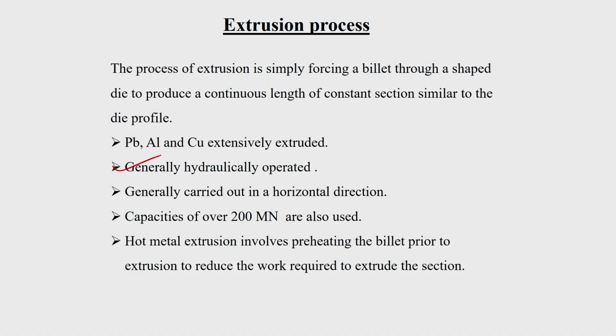Extrusion is generally hydraulically operated. In some cases there are mechanical presses, but normally it is hydraulically operated because this is done at comparatively low strain rate.